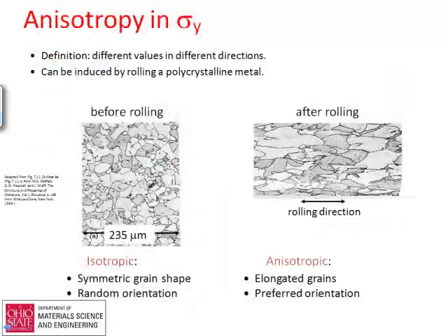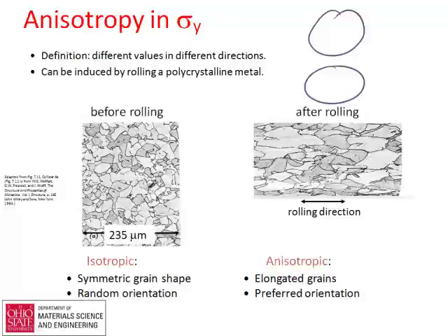The other thing, one of the ways we end up controlling grain size somewhat, or controlling lots of properties within materials, is by rolling. If you get Reynolds wrap, or the sheet metal that makes up almost anything that you buy that's made of sheet metal, it is made by a rolling operation. A couple big steel rolls, imagine those are round, and you've got material coming in at one thickness, hits those rollers, and comes out a reduced thickness. Steel mills are full of rollers, so this would be the final thickness. This would be the original thickness.